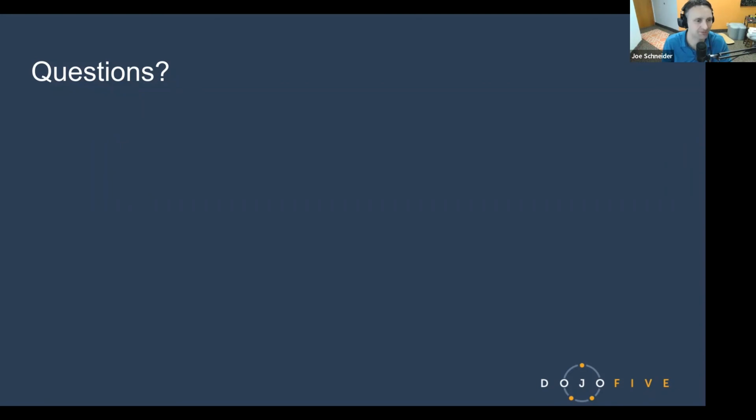Very cool. And then just a couple more commands. Another useful set of commands Steve's saying is something for fault injection, which would simulate hardware errors that are hard to trigger deterministically. I think you had mentioned that before, but that's super valuable. One thing I didn't put in this presentation, but I do have a list of must-have CLI commands. Maybe that needs to be another presentation, but it is things like inject faults, get software version, program MAC address, program serial number. This is when you're first integrating the CLI into your system. If you can come up with that list, manufacturing is going to need that at the end, and if you can have it right there at the beginning, it's even more useful for everybody.